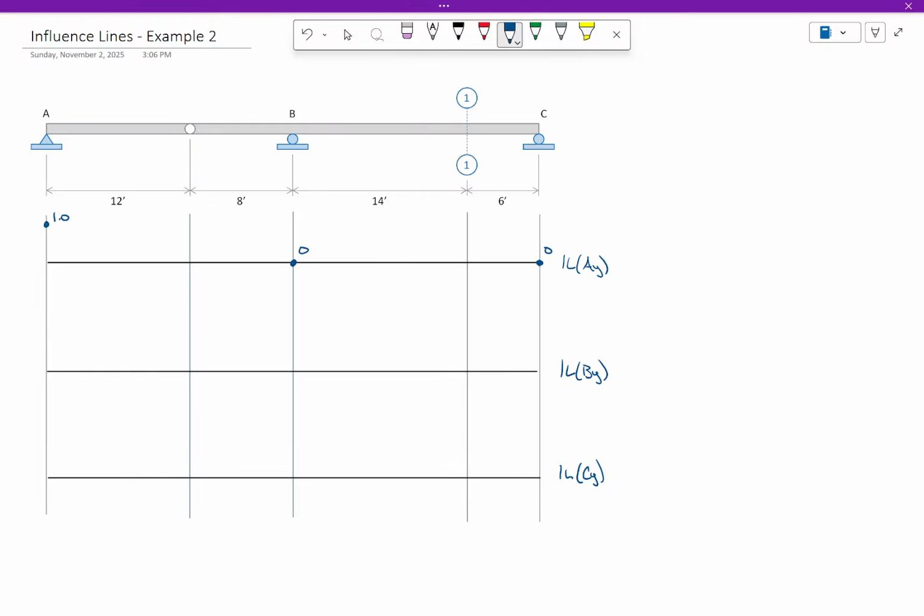Okay. So I'm asking you now. Let's work through this. Imagine in your head, this is a hinge. I kick out support A. I pick point A and I move it up 1. Tell me what the beam looks like once you've done that. And remember, no curves. There's no curves, and there's no hinges anywhere here or here. That's the only hinge. So what does it look like? What happens when you take point A and you move it up 1? What's it look like?